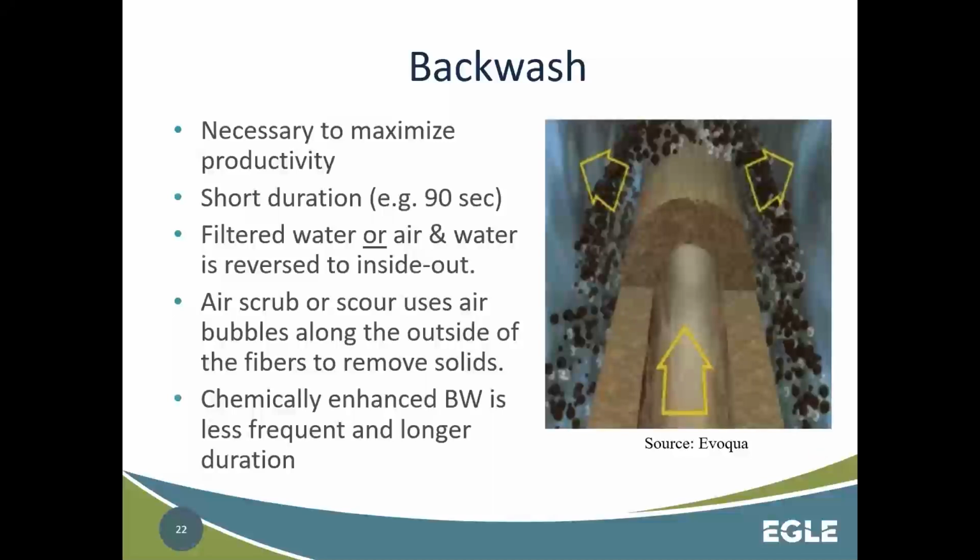All right. And I guess I should also introduce the concept of TMP, that's transmembrane pressure. So you're going to have some pressure loss. You measure the pressure out here and the pressure in here when you're filtering, you're going to have some pressure loss as it works its way through here.